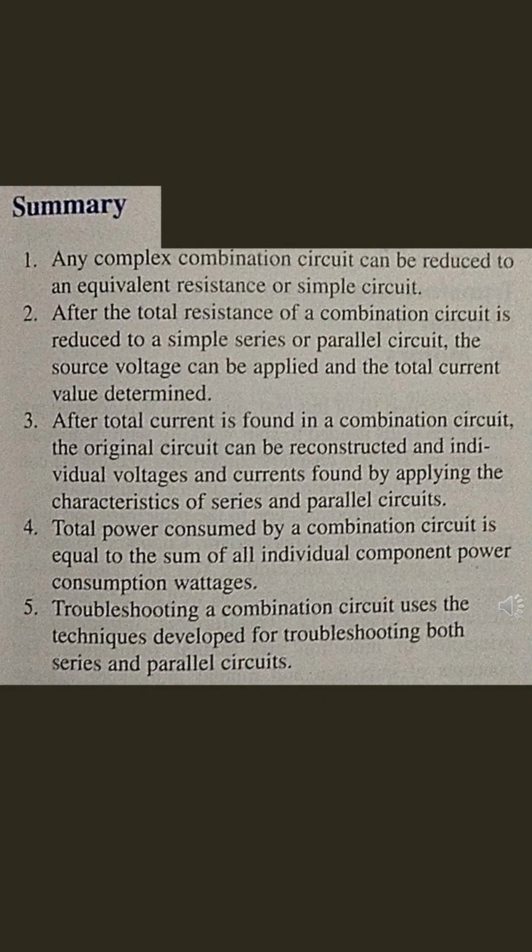Total power consumed by a combination circuit is equal to the sum of all individual component power consumption wattages. Troubleshooting a combination circuit uses the techniques developed for troubleshooting both series and parallel circuits.